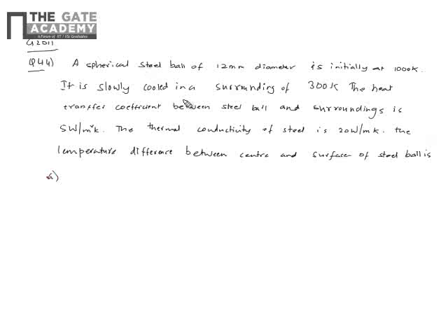It's a question on the lumped heat transfer analysis, and there are options. So option A is large because conduction resistance is far higher than, I'm just writing in a short form, convective resistance.